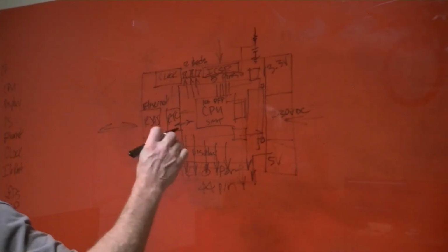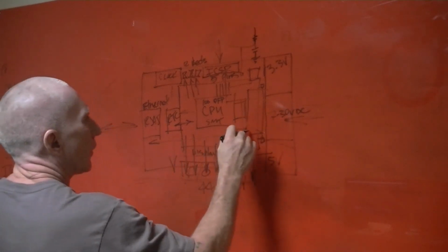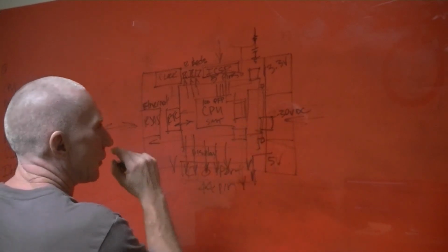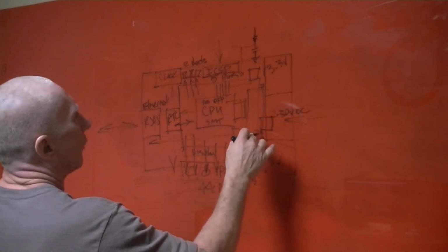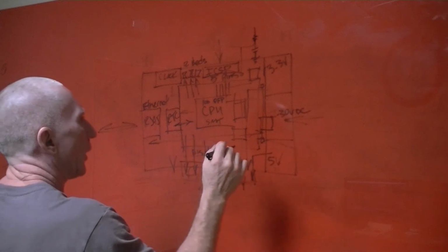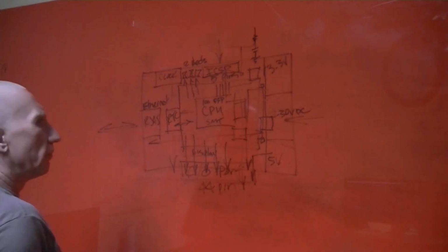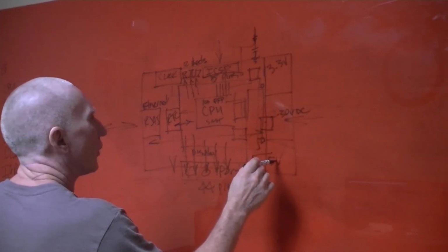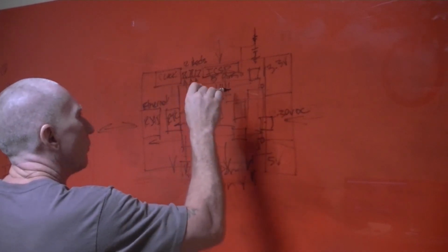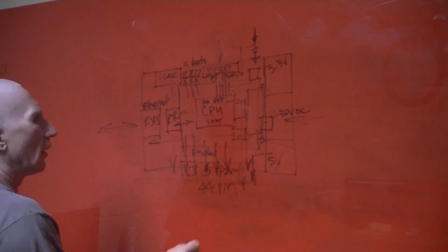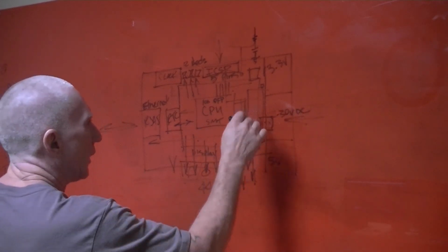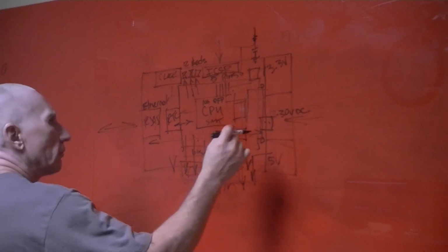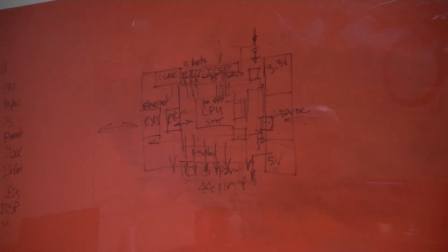And last but not least, we have a driver chip located right here. It's a 6-pin chip, and it is a current sink for the backlight of the display. We'll get into the actual technical aspects of each circuit later, but this sinks current. The 5 volts supplies the current to the backlight LEDs. There's 4 of them, and this sinks the current evenly among the 4 to make the display look a little bit better. And that's about it.